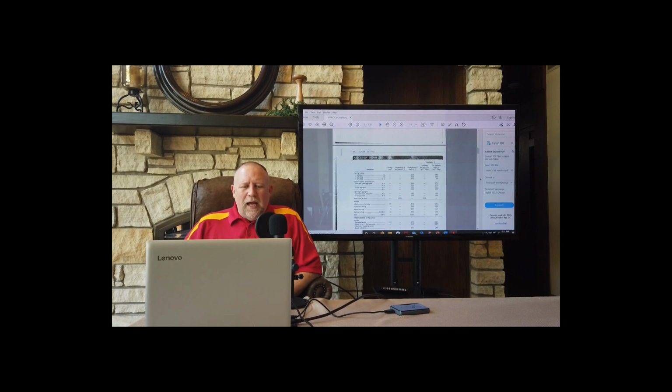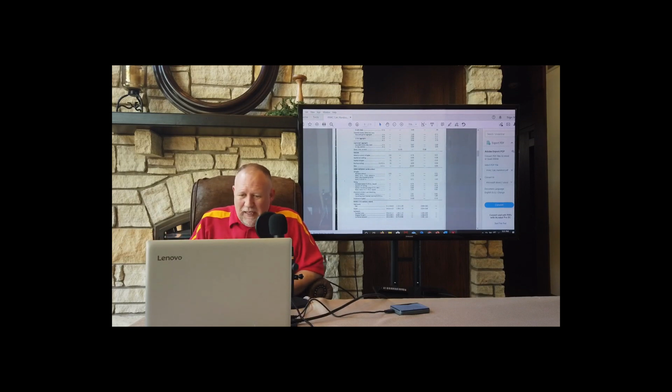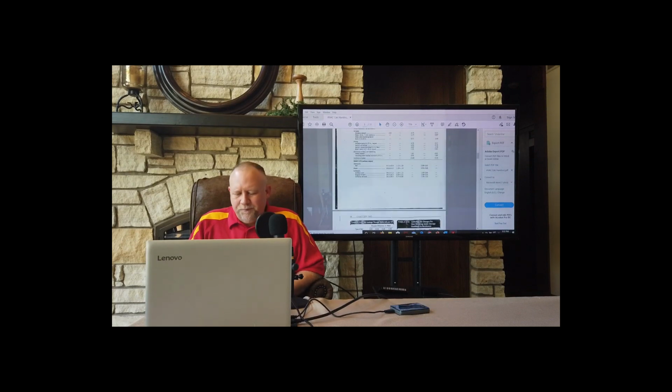All right, concrete block. The choice that you should use on this table is there's a choice between sand and gravel aggregate and cinder aggregates. Choose the sand and gravel aggregate. Very rarely are modern block going to be made with a cinder aggregate. There's also woods. You might need those, especially if we're talking about a wood frame wall that we're looking at. That's by and large the majority of the R values that you're going to use.